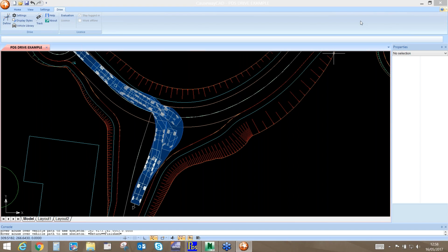One from Martin. Can you move other text apart from the manhole details? Yeah, so the manhole details are in a box, and as you noticed, when I was moving everything, all the text goes at one time, so it's always maintained within that box. We can move the pipe information, so when I was showing the diameters, gradients, and so on, those four, I think, and pipe length and type, there were four items of text. That is also deemed to be in a box.